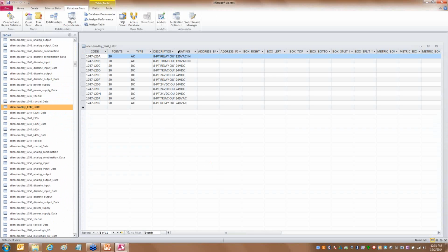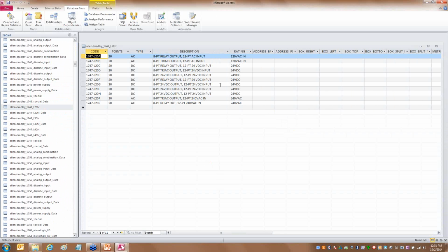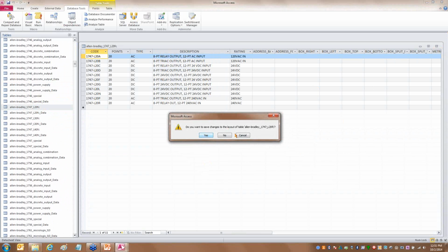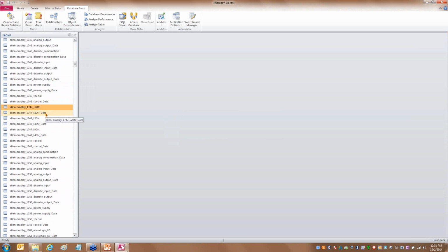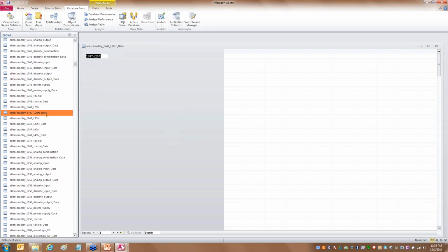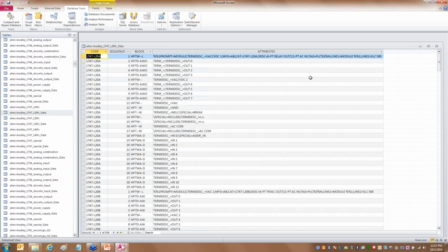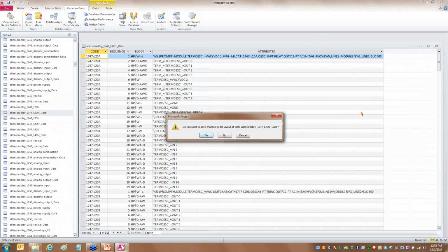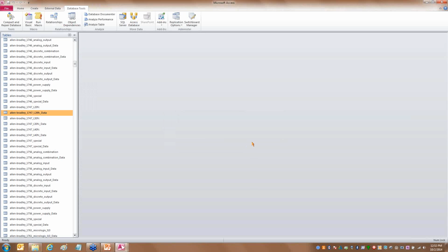So here's the one we were actually using earlier. And whoops, I'm in the module, in the wrong one here. It's the data one right here. And you can see it changed it in this one also. So a nice little routine. Goes through, searches through all that, made that change. Because it was one that I consistently wanted to change so that all my projects are using the same naming tagging convention for my PLCs as it is for my components, for my wire numbers, for my ladders. Everything's using the same system now because I've updated this file.